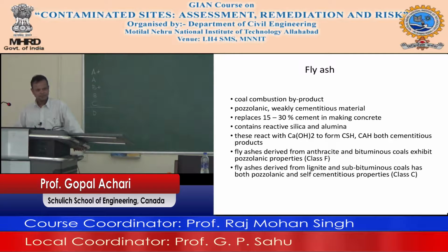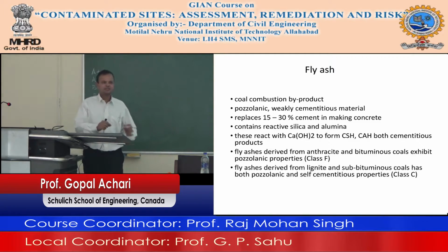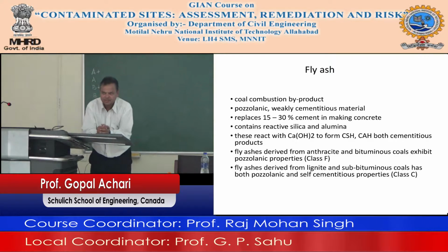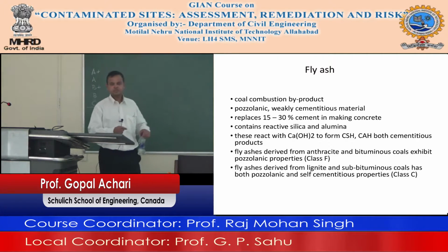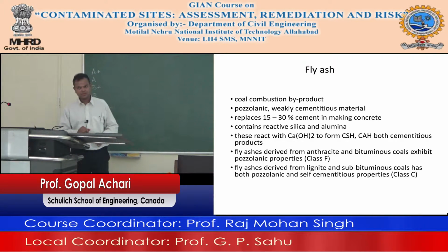Okay, a pozzolan is what? You add lime and water to it, it will form cementitious material. Okay, what do you have in cement as a byproduct? We just talked about it. What do we have in cement as a byproduct? I just said that. Calcium hydroxide, right? This said that it is alkaline. So we have calcium hydroxide in cement.